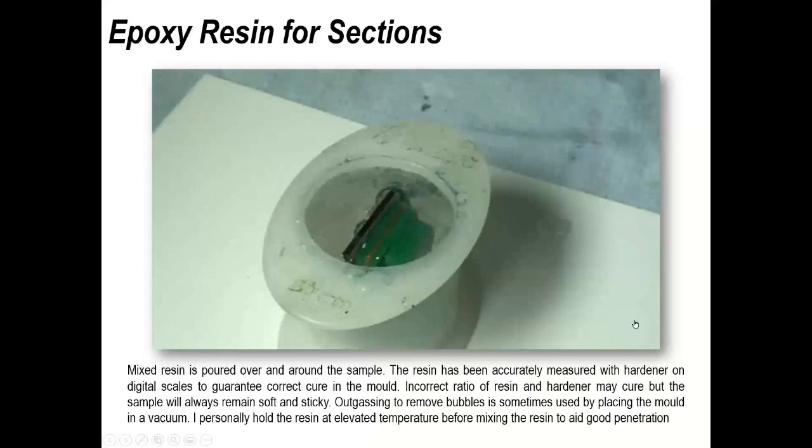If it's just a printed circuit board with some chip components on, a printed circuit board with solder joints on, then that's fine. But if it's something that's got a cavity in, ideally you want to fill it first. So as an example, if you were microsectioning a board which got an electrolytic capacitor on, it would be better if you could remove the capacitor body without destroying the solder joints.